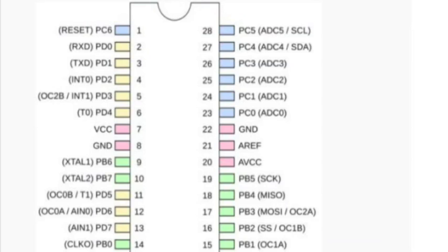The chips we'll be working with in particular look like this. I was talking about inputs and outputs and peripherals. So here's the pins. Just quick orientation, the AVRs are laid out in banks. So some of them are in B, some of them are in C, and some of them are in D, and I have them color-coded green, blue, and yellow here. They're scattered all around the chip, which is one of the things I like least about the AVRs.